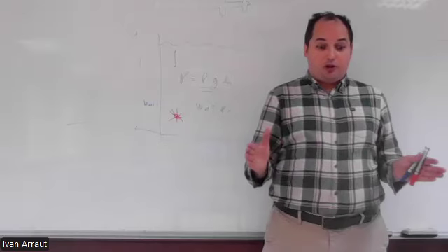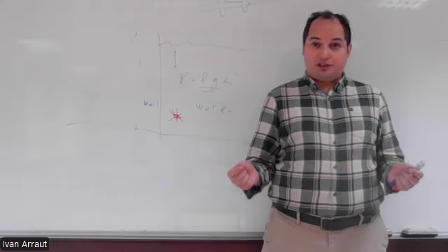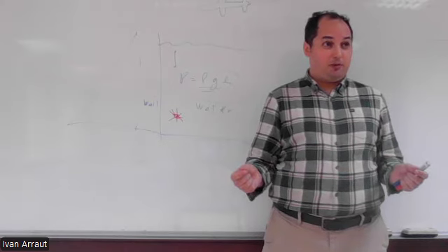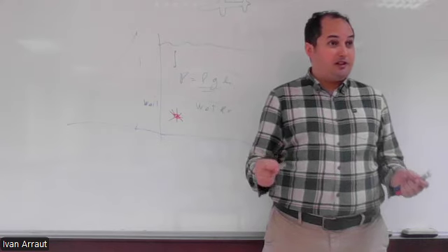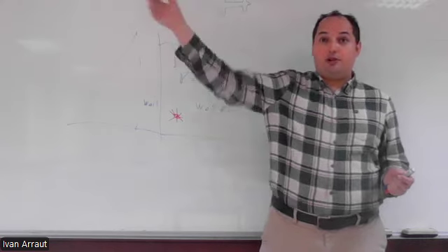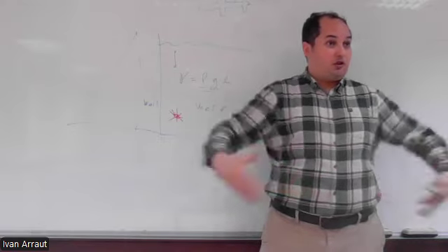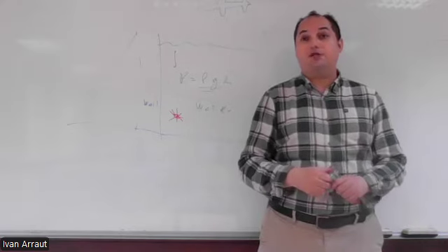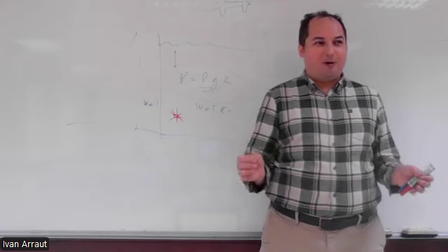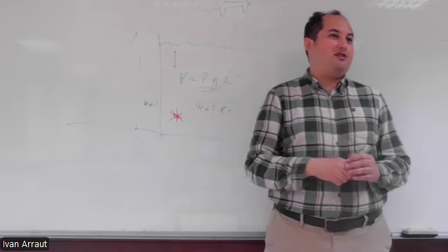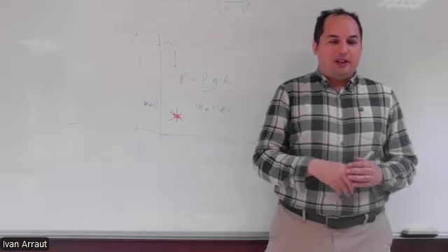That's why those planes that are traveling short distances, like 30 minutes, 40 minutes, have to be even more resistant to this kind of changes than the planes which are designed for long trips. When a plane is on a long trip, it doesn't suffer such a continuous cycle of expansion and contraction. But for short flights, this happens. So this is an issue which the designers of materials have to take into account, for example. Then the cabin is pressurized.